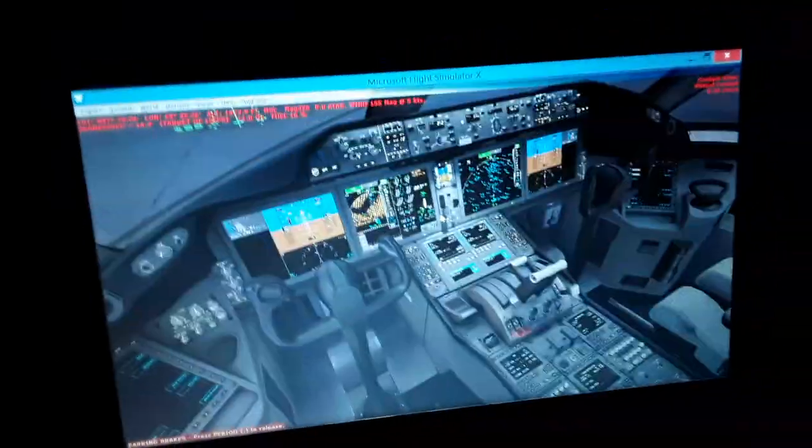So you're gonna see how we're gonna use the Boeing 787-900 for this flight. I'm also talking to you about the takeoff gross weight of the aircraft and the left and the right wing, how much fuel we have, 30% right now for this flight of the total fuel we can contain, and 10% in the center tank. So the flight management computer is going to calculate the center of gravity of the aircraft and aerodynamic chord position. I'm going to use 15 degrees of flaps and 4.25 degrees of horizontal trim stabilizer, calculated automatically using the flight management computer. Also, you're going to see other data we need to include.